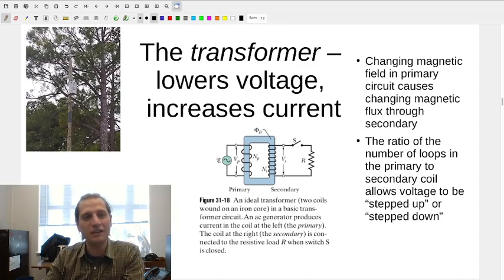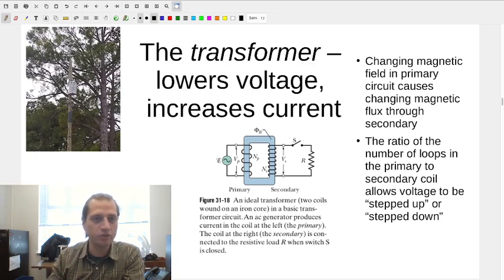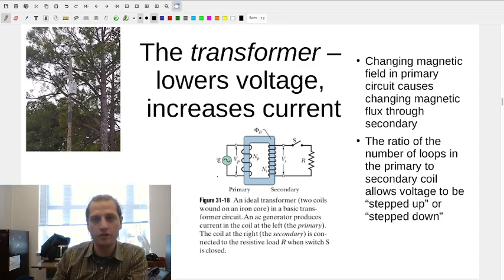What it's doing is lowering the voltage before it comes into your house. The key idea is that if you have a low voltage, you are going to have a higher current, and higher currents are, in some sense, more lossy. If you have a high current, you lose a lot of the juice, but you sort of want to get those voltages lower so they're a little safer to be around people. So this is the idea of a transformer.